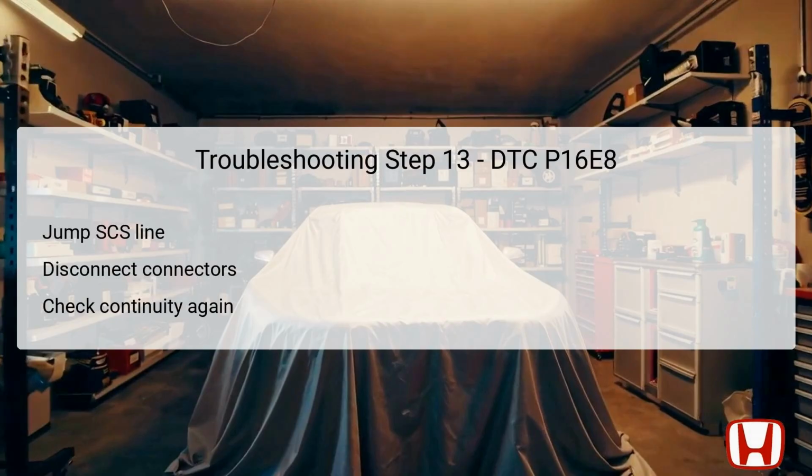The outcome will help inform you if replacing the shutter grille or further researching other components is warranted, provided the circuits behave as expected. In Step 14, the initial action requires the technician to ensure that the vehicle is turned to off mode to safely perform electrical diagnostics. The next step entails checking two specific fuses: fuse number A23 for the upper shutter grille and fuse number A22 for the lower shutter grille.